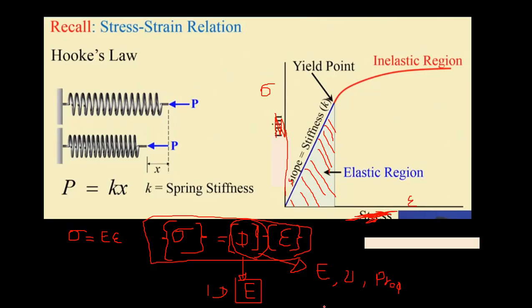And I'm repeating, this is the generalized Hooke's law for 1D, 2D, or higher dimensional elements. If it becomes 1D, you have only one stress component and one strain, that's axial, so this straight away becomes E: sigma equals E epsilon naught.